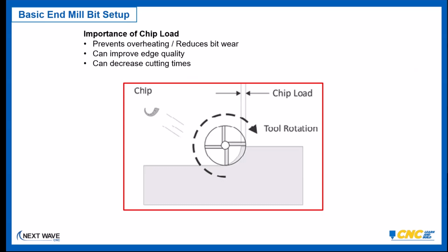If I'm cutting little parts or little holes, then I'll slow it down, because otherwise it starts to act a little like a sewing machine and it gets real jerky. So I just slow it down. Think about driving your car. You can drive around a big racetrack really fast, but going around a cul-de-sac, you simply can't go so fast. It's the same kind of principle here. So the smaller the area you're cutting, typically you're going to slow your feed rate down a little bit.